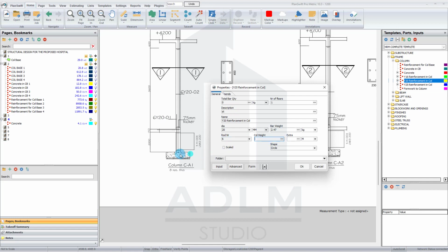Then the height, this is from this point down to the bottom of the slab. That's the ground floor slab. That's 2 meters, right? Now we have the extra. We have the one that will go through the slab. That's 0.15 plus the one that will come out, that you will join to other reinforcement too. Let's use that as 0.8, right? Then we have one more, which is the last one. The last one here is the bend that will go down into this point here. So that will be 0.4.